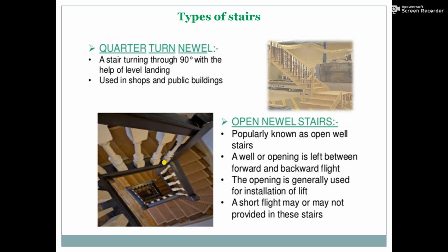The quarter turn newel. So quarter turn newel means what? Whenever we provide a stair running through 90 degrees with the help of a level landing, that type of stair is known as a quarter turn newel stair, used in shops and public buildings. So these types of steps are used in shops and public buildings. Then the next, that is the open newel stairs.